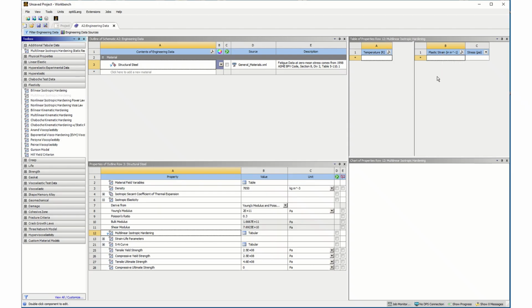So it is the net plastic strain, in that for your stress strain model for your material, you need to subtract off the elastic strain and enter in only the plastic strain with the associated stress. That's one thing that can catch you if you're not careful there.